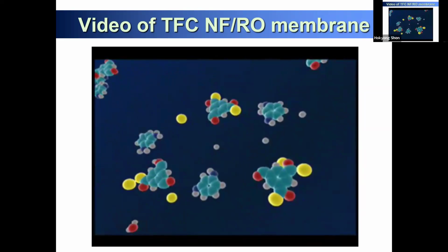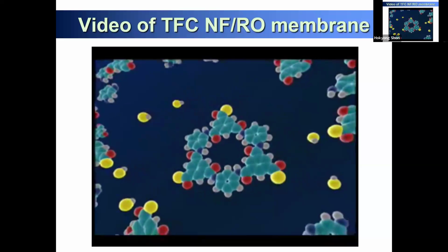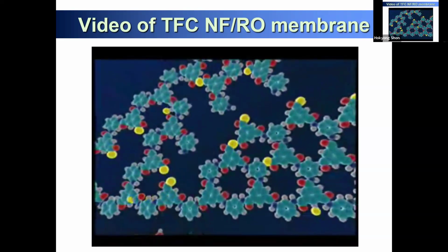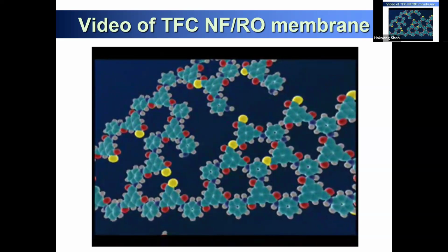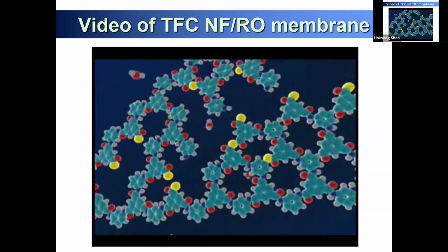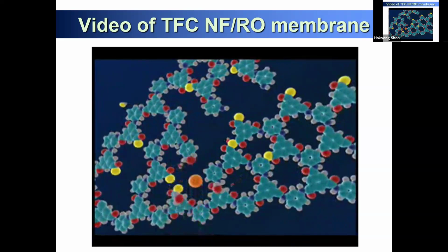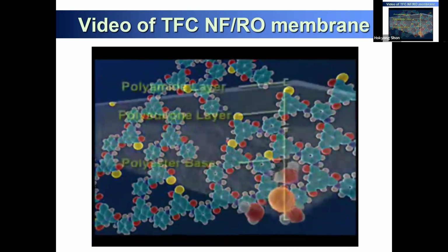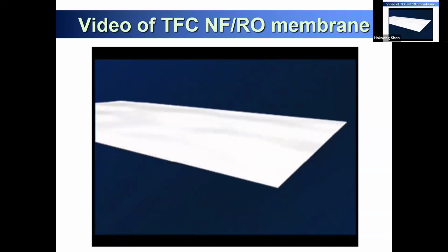Semi-permeable membrane skin is formed on the polysulfone substrate by interfacial polymerization of monomers containing amine and carboxylic acid chloride functional groups. Hydronautics manufacturing procedure enables independent optimization of the distinct properties of the membrane support and salt-rejecting skin. The combination of these three layers makes a durable membrane flat sheet that is used in each spiral wound element.